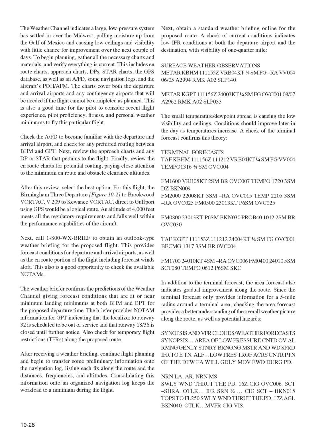The briefer provides NOTAM information for GPT indicating that the localizer to runway 32 is scheduled to be out of service and that runway 18/36 is closed until further notice. Also check for temporary flight restrictions, TFRs, along the proposed route.